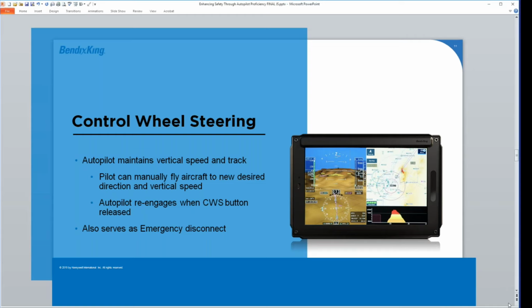Yeah, absolutely. And we kind of cheat in some of that because modern autopilots tend not to go off in random directions like we're used to, where we engaged our analog autopilot of the past and the heading bug's not set exactly right. I always forgot to set the heading bug, and so inevitably I'd turn the autopilot on and away we'd go on some 45-plus degree turn. Those are things we don't run into with these types of autopilots, but control wheel steering makes it even better.